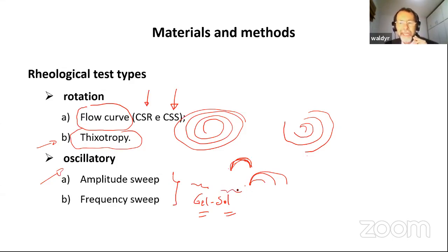Because our material in the tailings deposit probably is going to be in a gel state, you want to understand if this material can be in a sol state, or a liquid state. You have to understand this in order to do a rationale on mud flow. Otherwise, you don't understand what you're doing. That's why we invest a lot in rheological test types and understanding which test can give you what you need for your application.